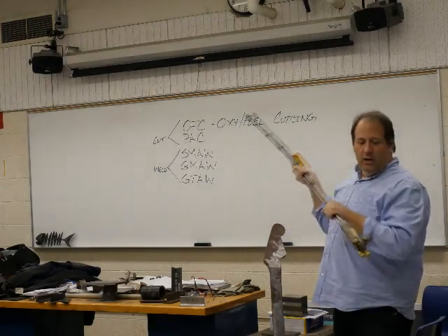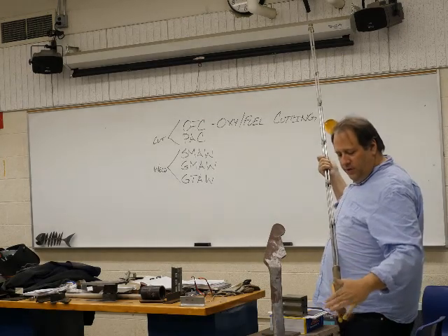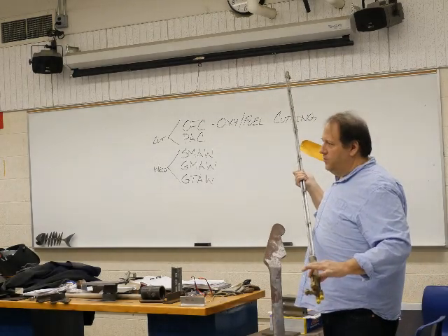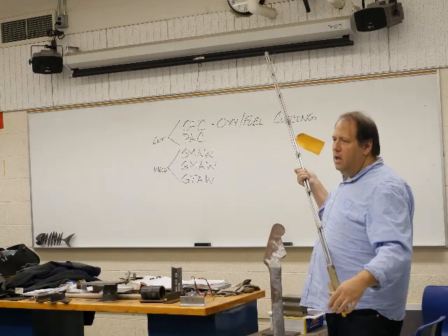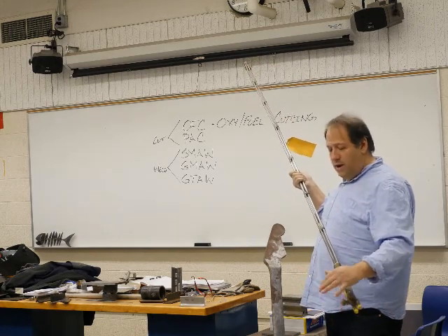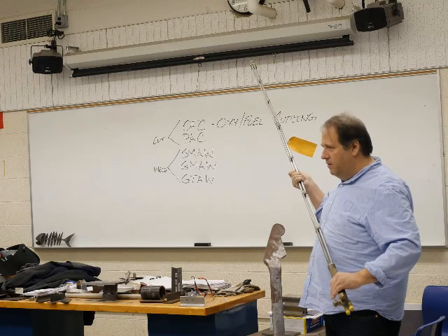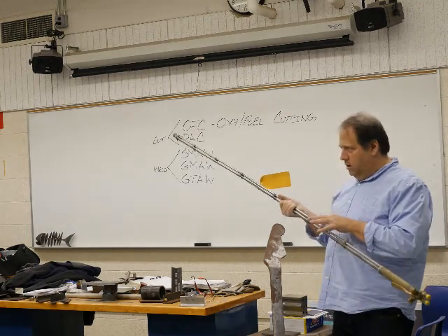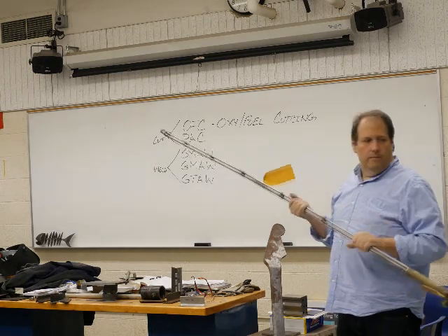So what I was actually going to show you though, these are your two valves, and then this here is the oxygen valve for the high pressure stream. So you would have this on, you would have a flame coming out, that's your preheat, you push the lever down and cut, that gives you a high pressure stream going through. You've got three tubes here.